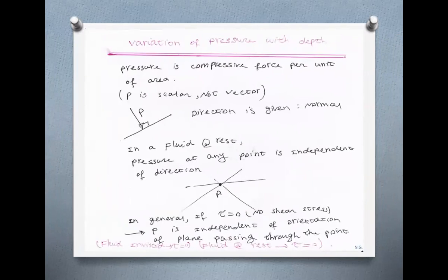So last time I asked you a question: what do we mean by pressure at a given point in the fluid? And the answer was, you consider a differential cube around that point, such that the point is in the center of the differential cube, and that cube has 6 surfaces. There is pressure on the top, bottom, right, left, front, and back surfaces.